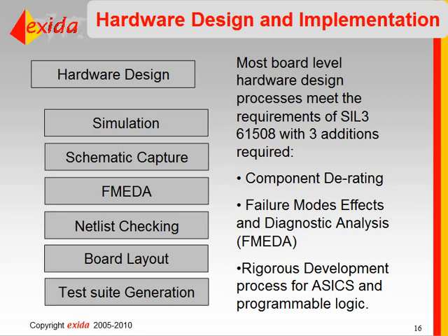And there are other standards out there that provide more specific guidelines for that. Failure modes, effects, and diagnostic analysis is an expansion of the FMEA that we just talked about. It goes beyond just looking at what the failure modes are and what diagnostics you have in place by adding a quantitative side to it, where you can actually calculate now what the failure rates are in terms of types of failures. So what's your failure rate for dangerous failures, for safe failures, and also in terms of detection, what percentage of those failures will be detected by diagnostics.